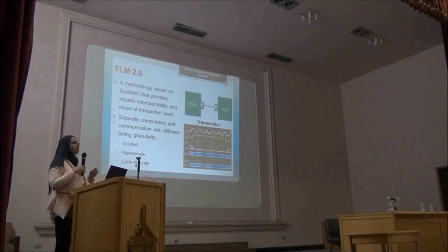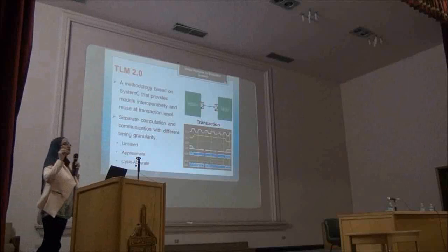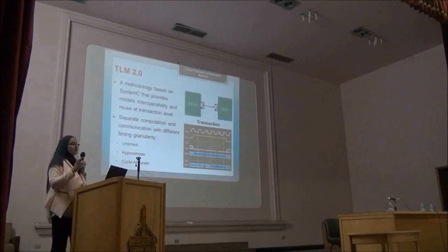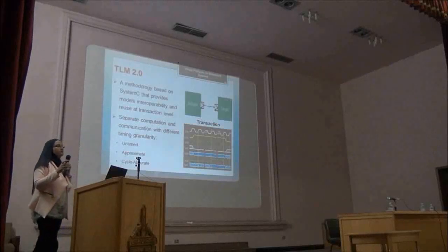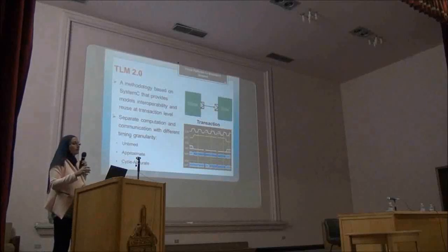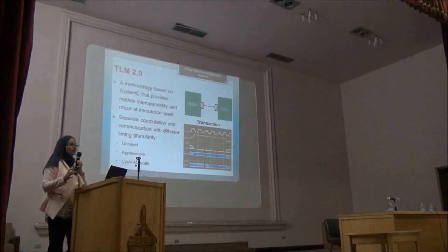So transaction level does not care about signals and abstracts all this signal interaction into read and write transactions between the initiator model, which is mostly the CPU or the processor we have, DMA processor, DSP processor, and the target or slave device, whether it is a memory or any other slave peripheral.